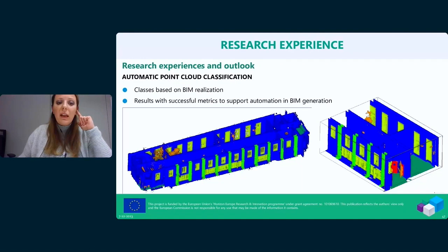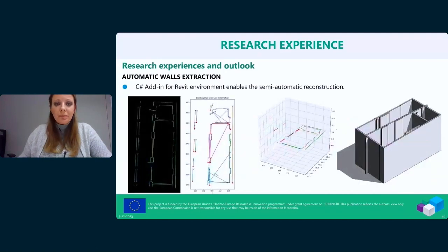So basically we can semantically enrich our 3D data and divide it into clusters of points belonging to a particular class. And this is quite important for the possibility to work in a BIM environment with fewer data, so single classes like walls or windows or pillars and so on, and have a more manageable environment.